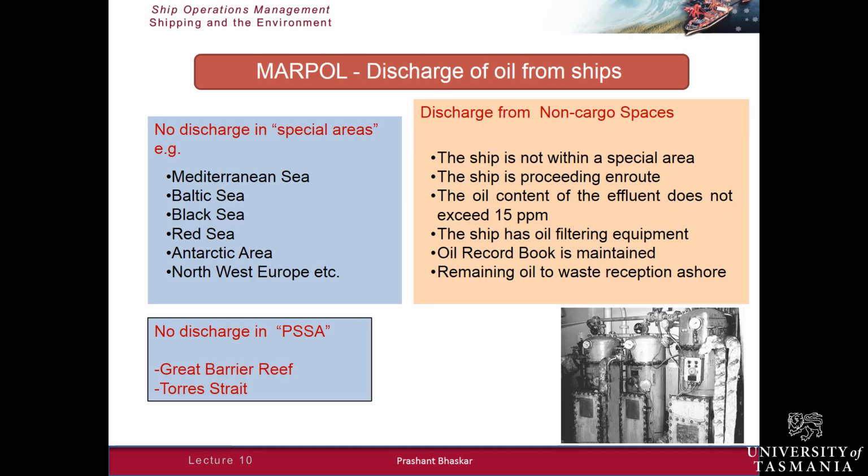Very, very quickly, just to give you an example of the type of requirements stated under MARPOL. So if you look at MARPOL Annexure 1, that talks about discharge of oil. And if we talk about discharge of oil, first of all, the ship has to be outside special areas. And the special areas are the enclosed seas of the world, like the Mediterranean Sea, Red Sea, etc.